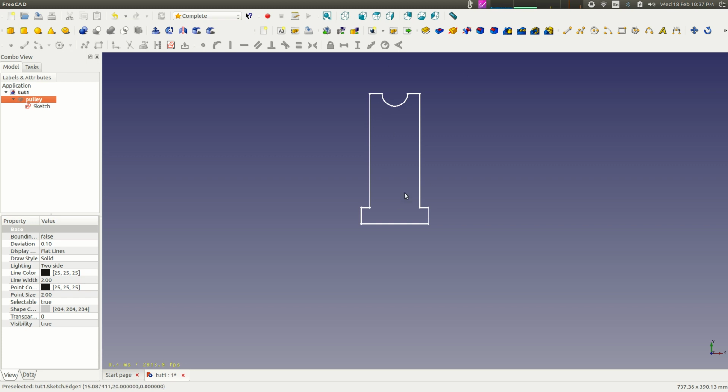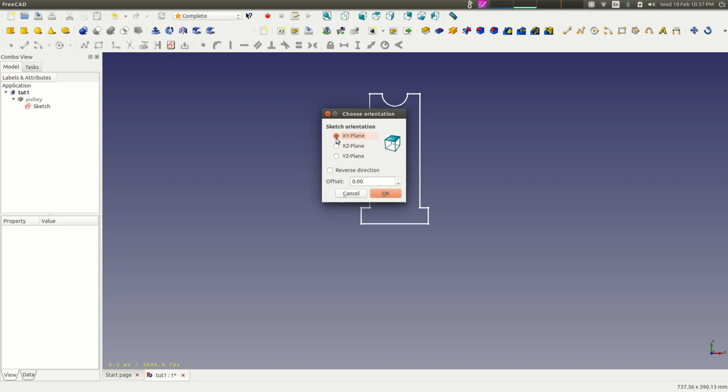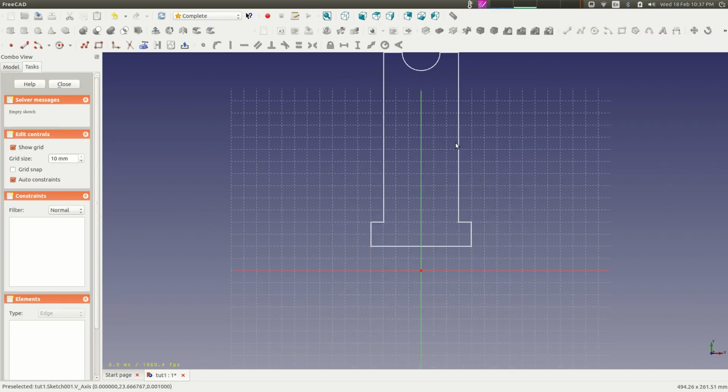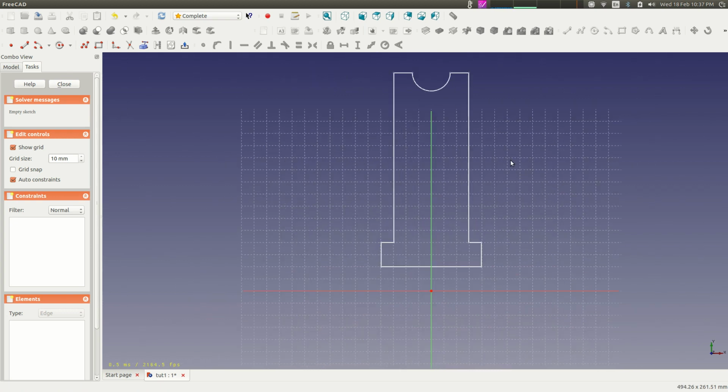So we're not going to edit this sketch. We're just going to keep it, because it can be more complicated to try to constrain something with that funny looking thing in there. So a lot of times it's easier just to make two sketches and cut one from the other using what are called Boolean operations. So what you're going to want to do is make another sketch. So we'll go create new sketch, make sure it's in the same plane, press OK. So we're back to Sketcher here. We can't edit this sketch. This sketch is just kind of there, so I know what I'm drawing over.